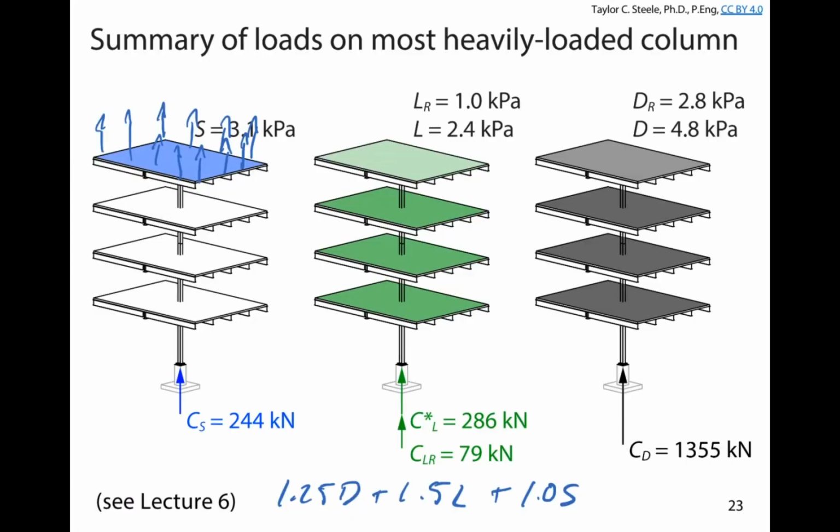Did anyone calculate this? If I was to say the number? No. I get a value of 2,367 kilonewtons. How I'm going to denote that is I'm going to use C subscript F. Subscript F means factored. I've applied my NBC load combinations to get the maximum factored column force from the loads present on the column, including that uplift that we might get from the roof level.